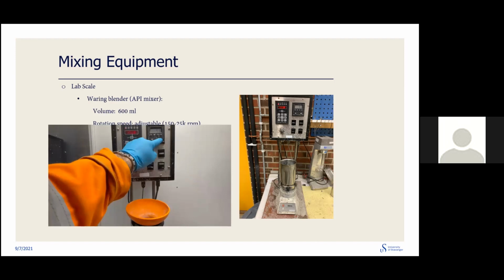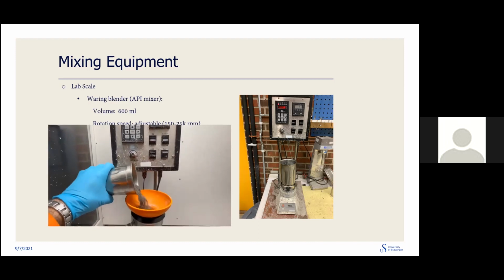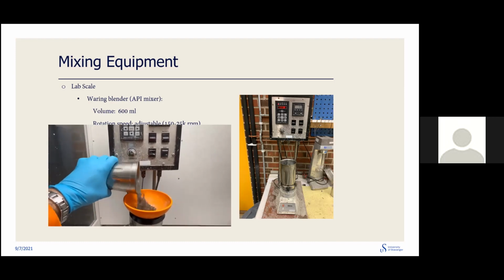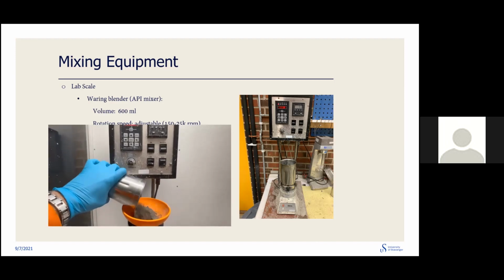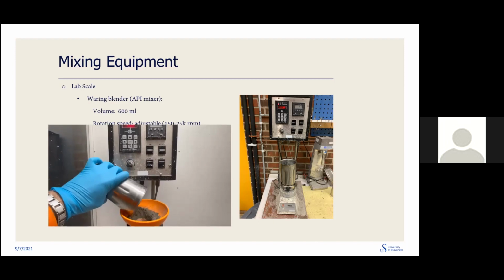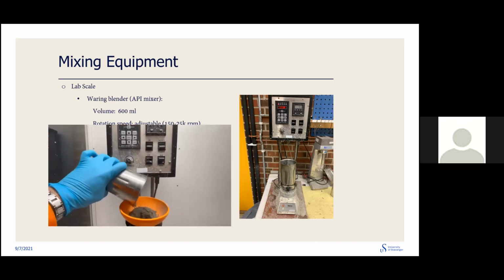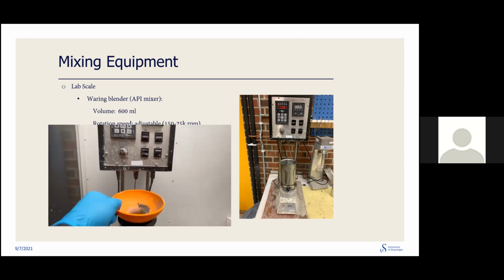So how do you prepare the cement based on API recommendation? I use Class G cement, which should be 44% by weight of cement mixed with water. You have 15 seconds to add cement to the slurry while it's being mixed at 4,000 RPM.